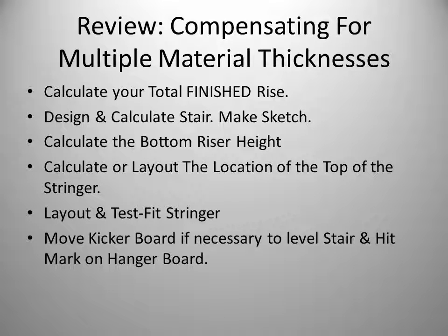Once we've calculated our total finished rise, then we can design and calculate the stair. Do not calculate the stair based on the subfloor to subfloor rise. Be sure to make a sketch so you can keep track and visualize the various thicknesses on each of the parts.